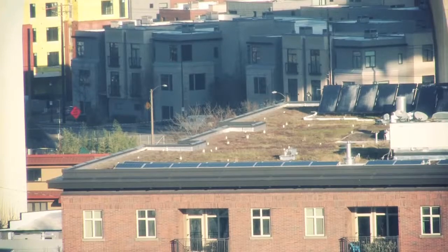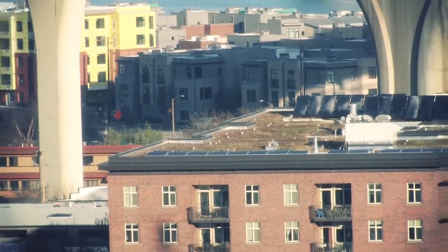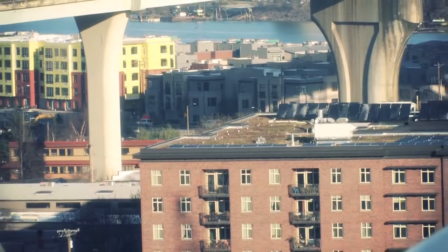Green roofs have been implemented in Portland for about 20 years, and they started as an experiment. A coworker at the City of Portland had been to Europe and was inspired to try a green roof on his own garage. And like with other green infrastructure tools, the City of Portland studied the performance of these on a small scale and found that they were very successful at reducing volume and reducing flow to address some of the capacity problems in our sewer system, in our storm system. So green roofs allowed us to treat an otherwise unused space on a rooftop and turn that into a resource for our systems.